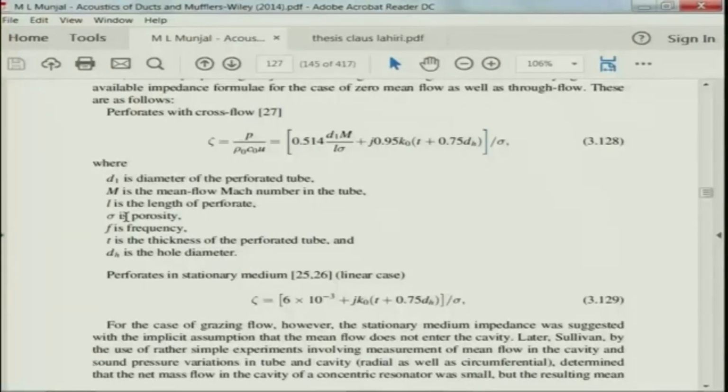So, 30% porosity means it is highly porous and acoustically transparent, as though waves can go from the inner pipe to the annular section without much obstruction. Acoustically speaking, it is as though the perforated bridge does not exist.